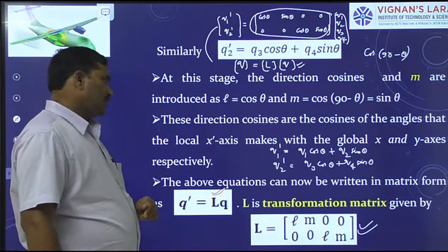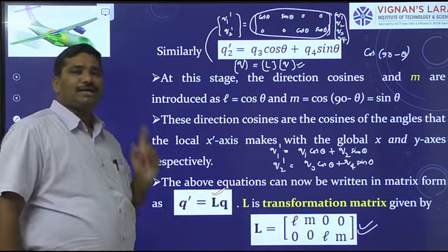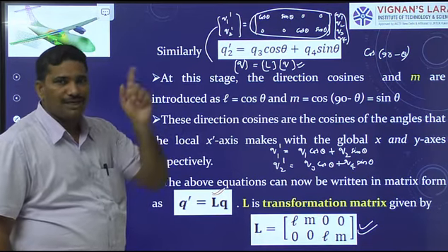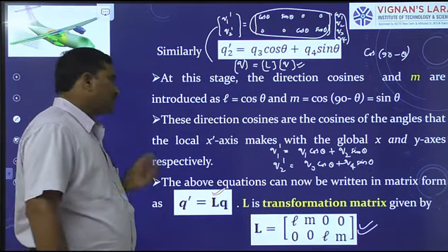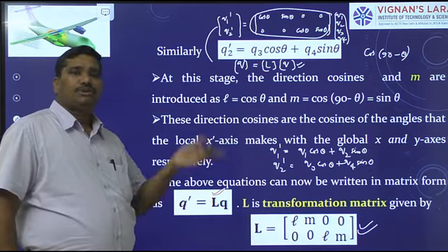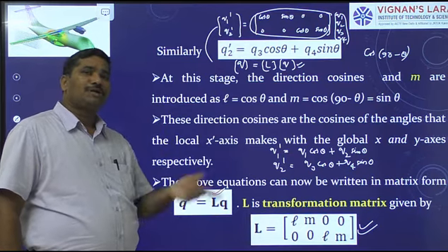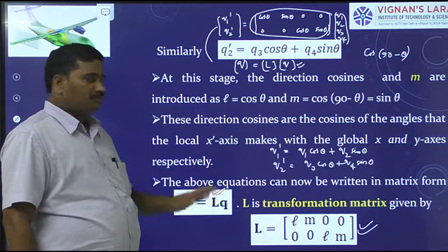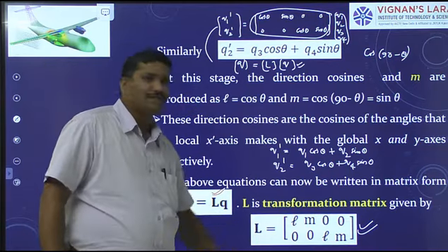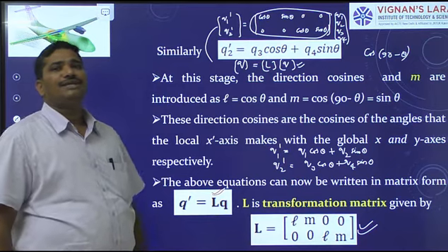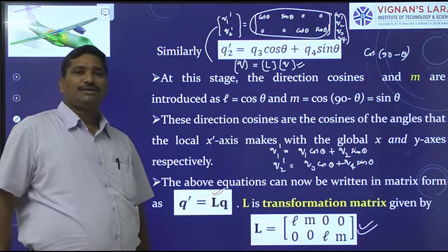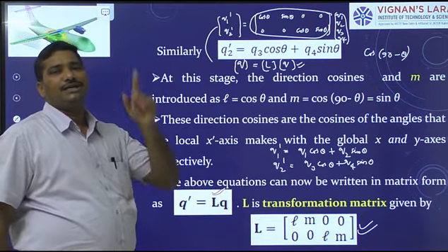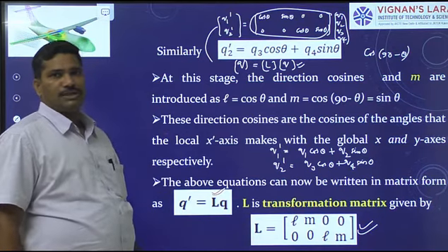We derived the expressions to determine the nodal displacements with respect to local reference frame and transferred them to the nodal displacements with respect to global reference frame. From them a transformation matrix is derived which consists of the direction cosines, and it depends on the values of the direction cosines. Okay, thank you.